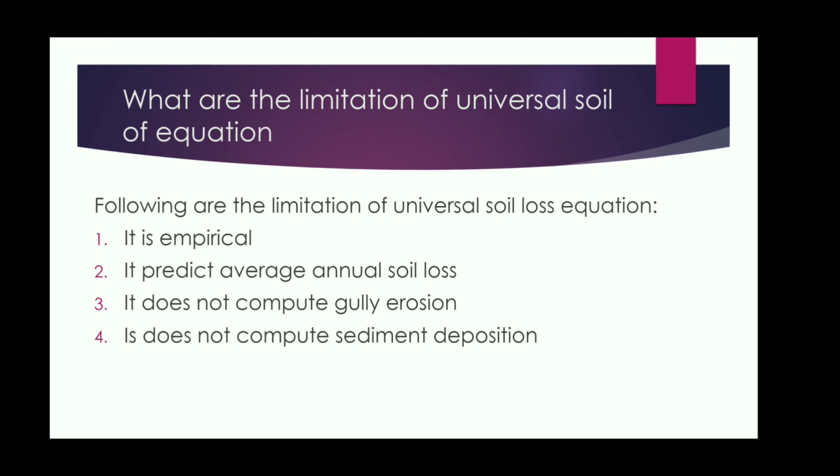What are the limitations of universal soil loss equation? Following are the limitations of universal soil loss equation. It is empirical. It predicts average annual soil loss. It does not compute gully erosion. It does not compute sediment deposition.